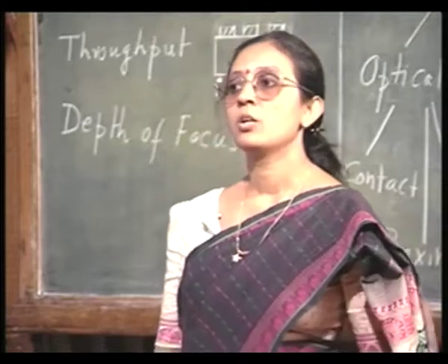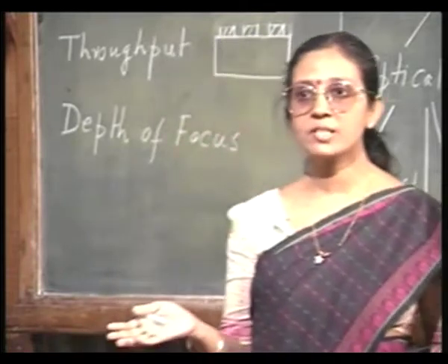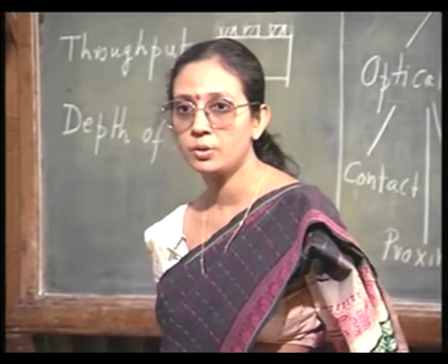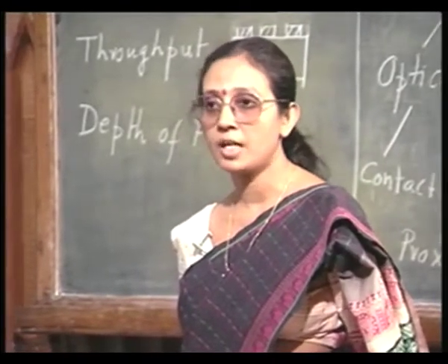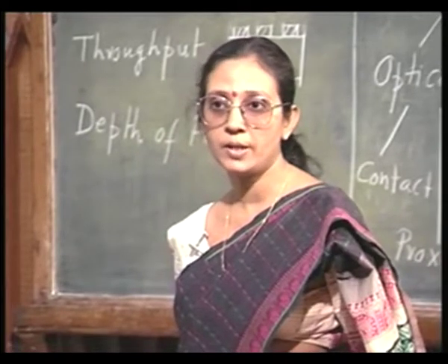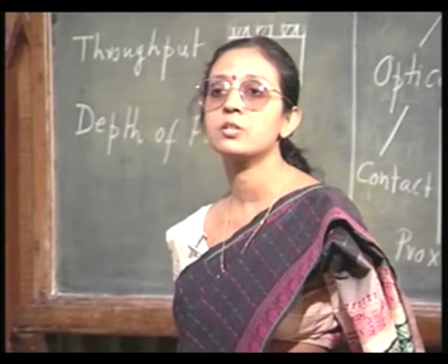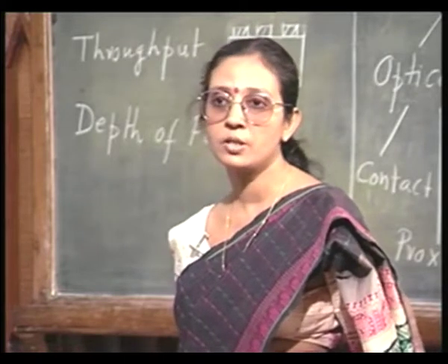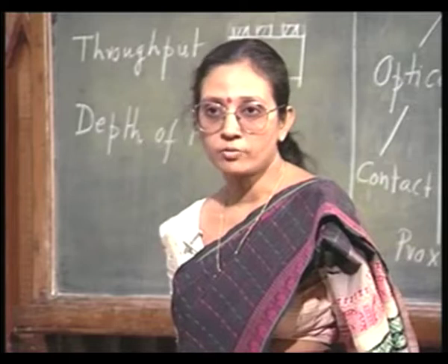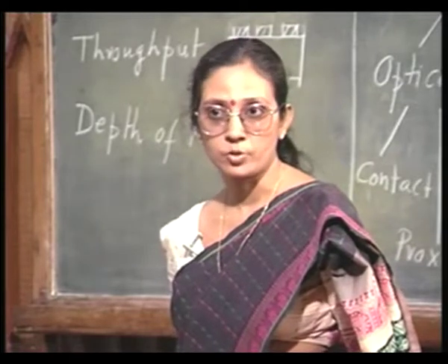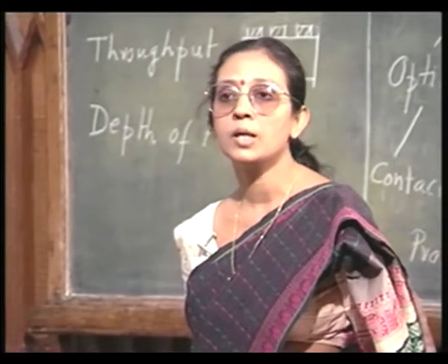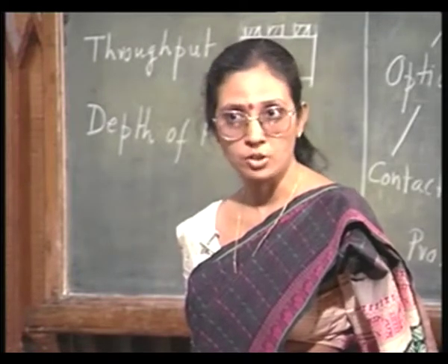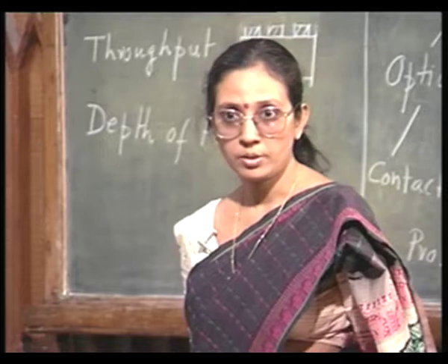Okay. So, we have discussed the process of optical lithography. In optical lithography, I can have 3 types, 3 subsections depending on whether the wafer is in contact with the mask or not. I can have 2 types of resist depending on whether it gets softened or hardened on exposure. And I have also told you what are the basic chemistry behind this hardening and softening.